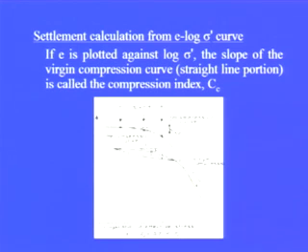So here from these two we can obtain the compression index Cc as well as recompression index Cr. Now this recompression index is the average slope of this curve of the expansion as well as recompression. So here this compression index is nothing but the slope of the virgin compression curve for the case of the normally consolidated clays, whereas this slope is the slope of the recompression curve.